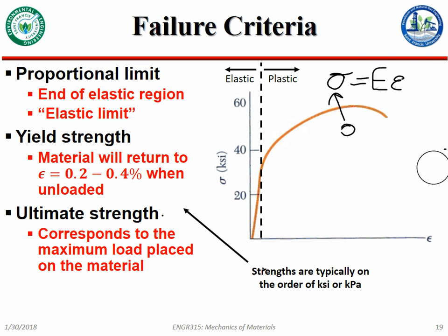And that's important to us because something can yield without breaking, kind of like the axle on one of the intro to engineering trebuchets last semester. The thing was bent in a V, it wasn't broken, but it definitely yielded and you couldn't actually use it for what it was intended for, at least not very well.